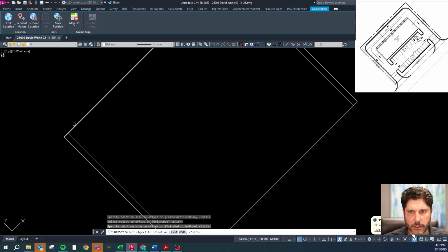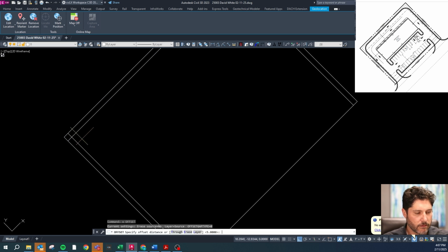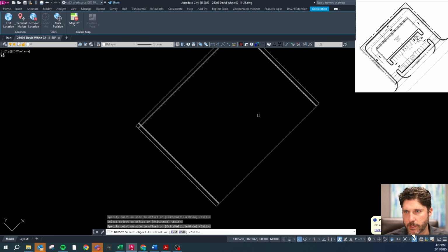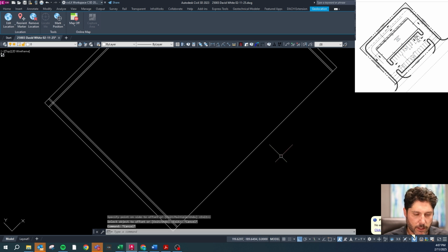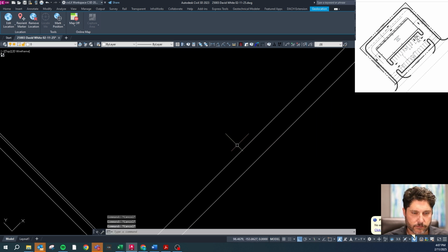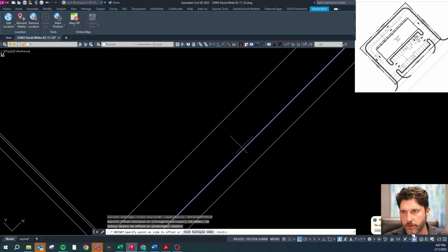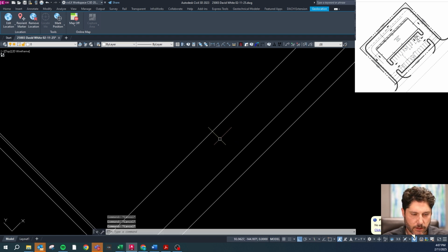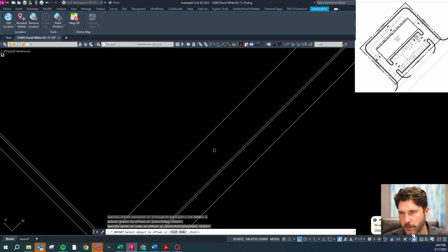and this side, and then my curb is generally going to be 1 foot off. That's our standard practice there. And then I have a 10-foot landscape on the front, and then a 20-foot building setback. We'll go 1 foot off of that landscape strip, and then we're going to start wireframing our site.